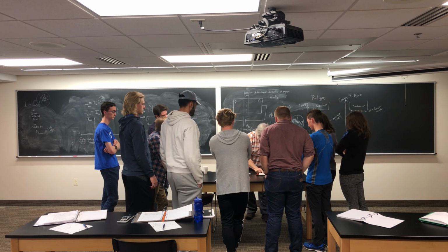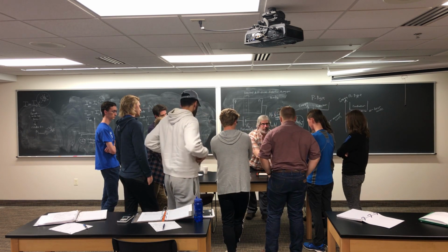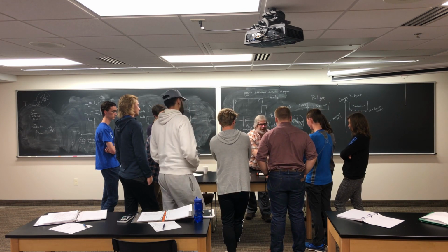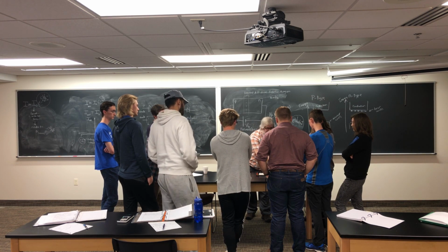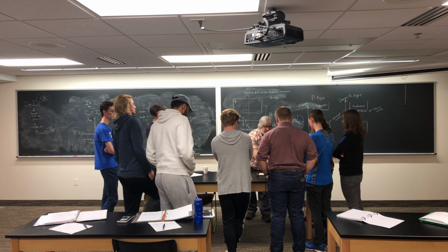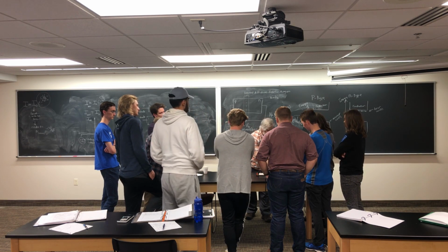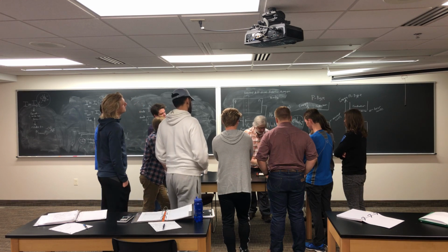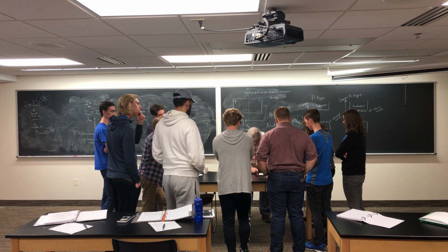Okay. I'm going to run it first through this ammeter, see if we have any current. So I'm going from the positive side of my battery here, to run through this analog ammeter. You got to have it connected, right? The positive side of it goes closer to the positive side of the battery for these little ammeters. So I'm going from there. Then it's running through the ammeter, the current is, and then I'm going through the resistor to the positive side